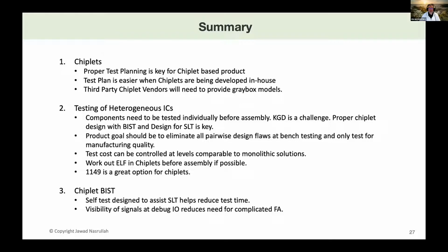What typical failures do you see right now for chiplets or at these interfaces, and how do you guard against them? Yeah, so two classes. Number one, maverick lots coming in for these components, and you are confused, like what just happened? This component was working fine, but the supplier just supplied some bad parts. That's kind of out of your control, but you have to catch it and send it back, right? The second one is assembly related issues, and there is a whole bunch of that.